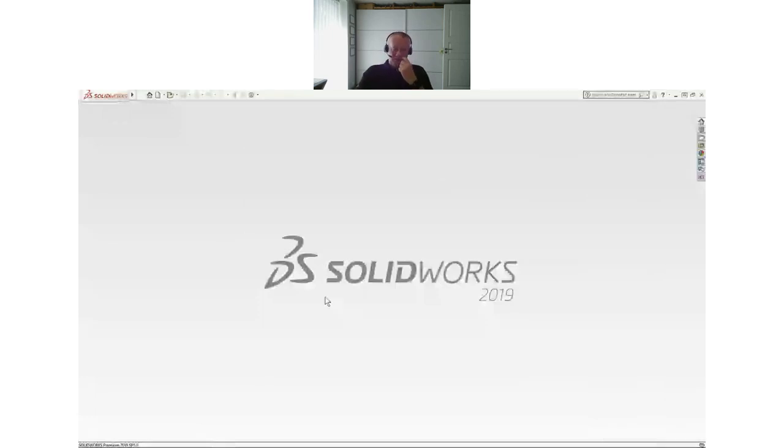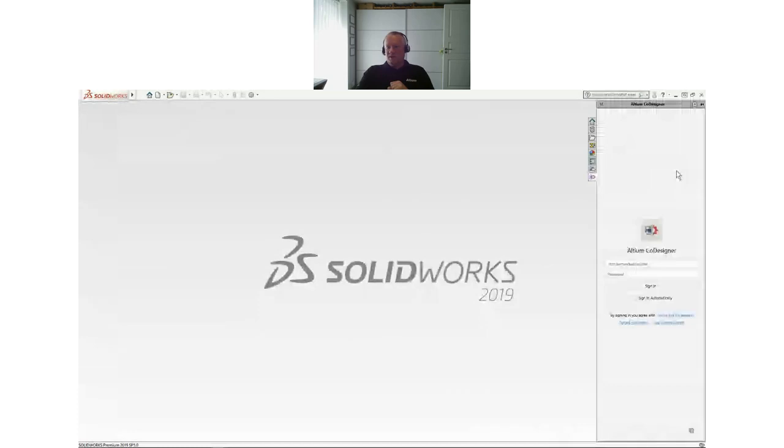So this is my SolidWorks here. And in SolidWorks, I have installed an add-on called Altium Co-Designer. Now, this can be downloaded from our web page, and it's free of charge. There's no additional license fee from Altium or from SolidWorks, actually. So I'll just use this add-on here. It will ask me to sign in, so let's do that.